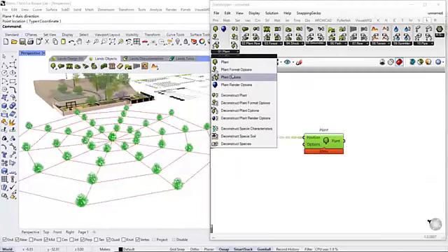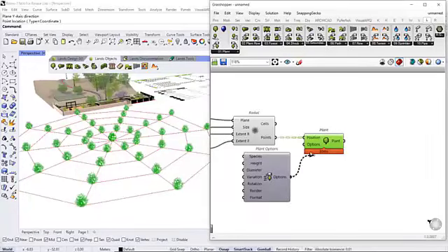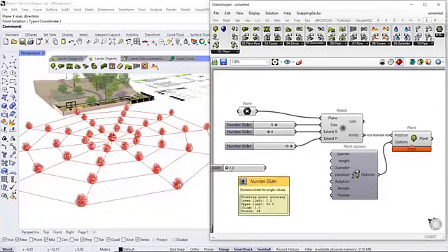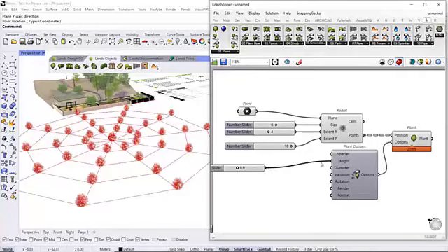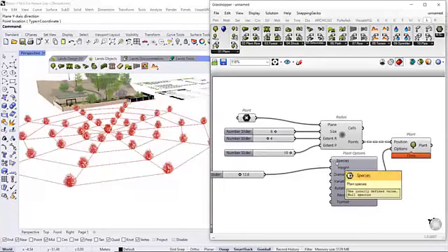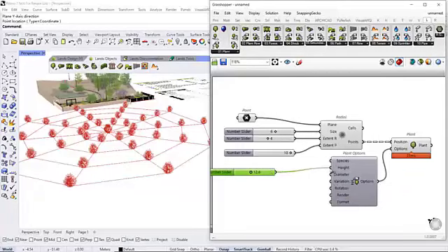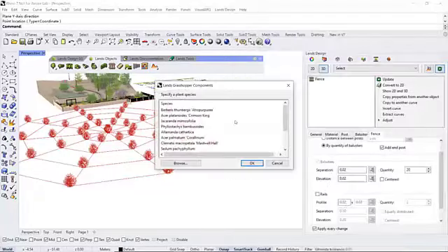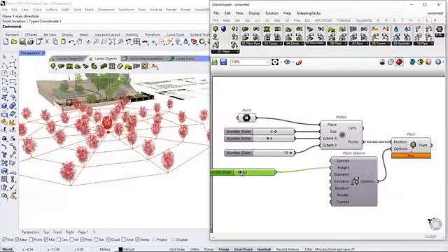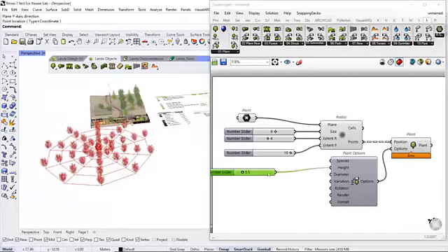If we want to change that, we have the plant options. And now with another numeric slider that maybe goes from 1 meter to maybe 30 meters, we will be able to change the height of these plants. Well, if you see that the height doesn't change, probably we're using a species that has a maximum height. You can just right click here to set a different species. I'll select that one. And now this is a bigger plant, so we'll be able to change the height here.